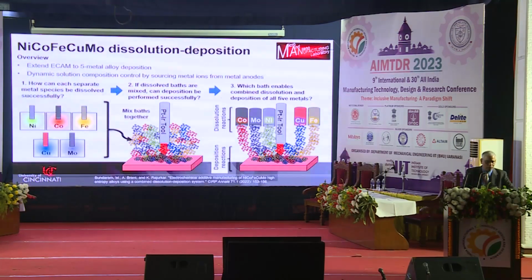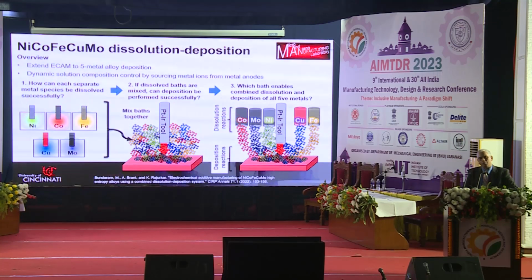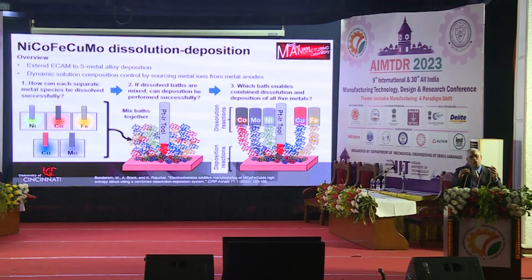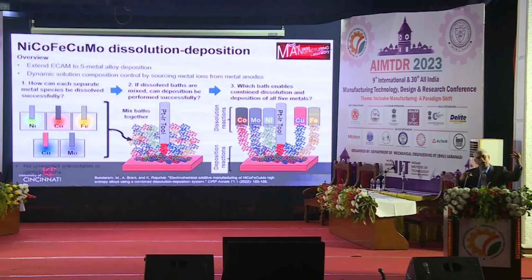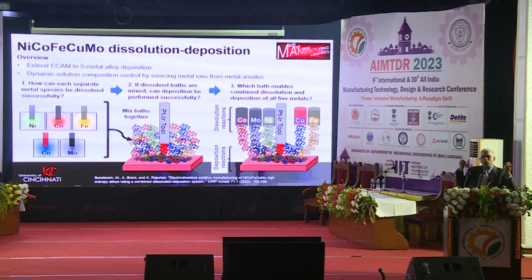It is not like a freeway path. Now, this is fine. You can have the salt solution and do that, but if you really want to make it a commercial system, then you have to have a mechanism where, whatever metal you want to deposit, you have it as a sacrificial electrode, in solid form. You get the ions by dissolution and do the deposition, right? That will be more straightforward.